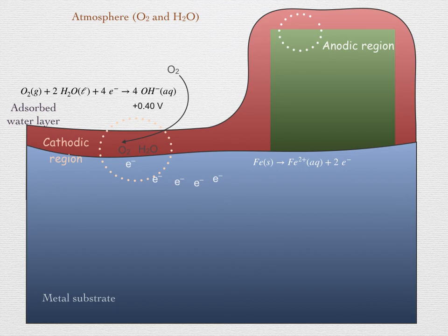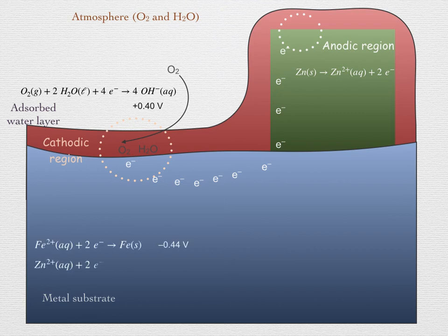What is required is that we have a good low-resistance path for the electrons to migrate. Looking at the standard reduction potential table again, we see that there are many metals more negative than iron. However, the least expensive one turns out to be zinc. A steel-hulled ship, for instance, is subject to corrosion, but bars of zinc metal are bolted to its outer surface.